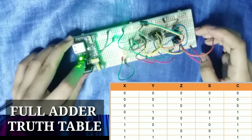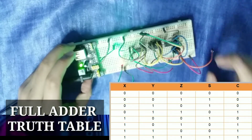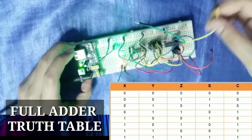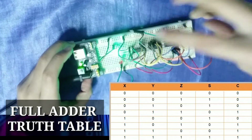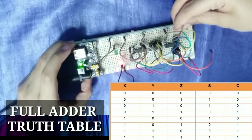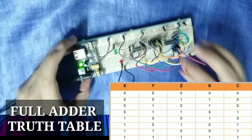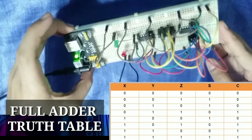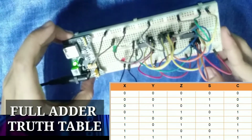Now for our truth table, let's turn on our voltage supply. If all of our inputs, X (the yellow wire), input Y, and input Z, are grounded, as you can see, both our S and C outputs, the green and the red LED, are turned off.